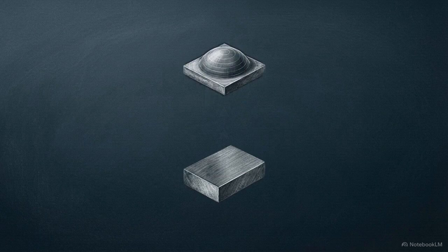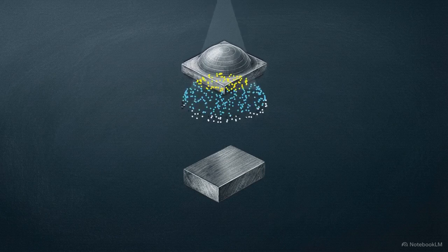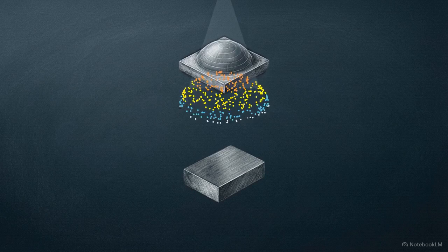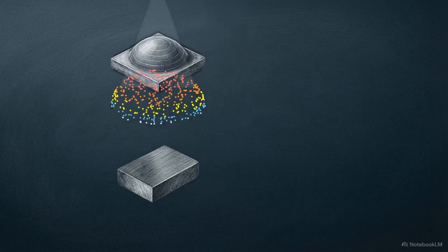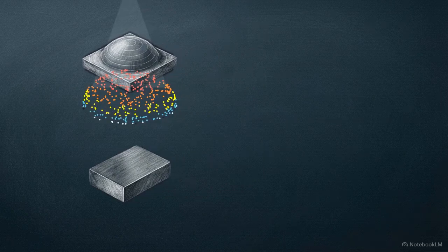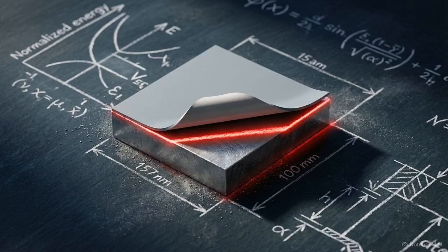We then add a metrology layer called digital image correlation, or DIC. DIC is an optical, non-contact method that tracks surface changes in real time to calculate strain. As the blister expands, DIC provides high-resolution tracking of the deformation and strain fields across the surface of the coating. This raw optical data is fed into an FEM computational model, which integrates the visual strain mapping with numerical stress analysis. The final analytical output of this combined system is a measurement known as normalized energy.